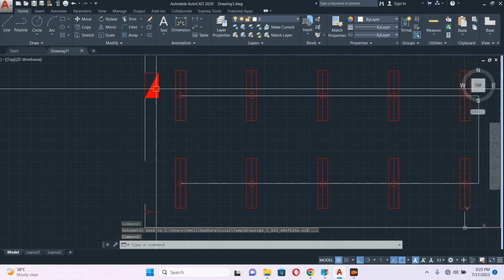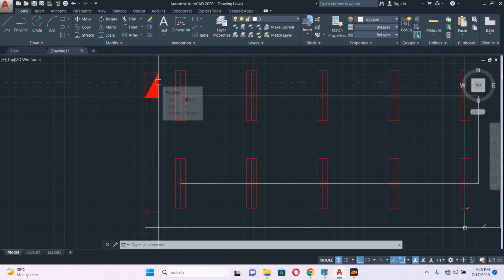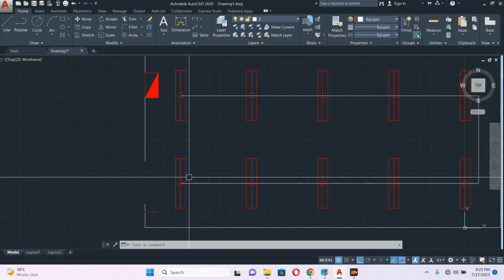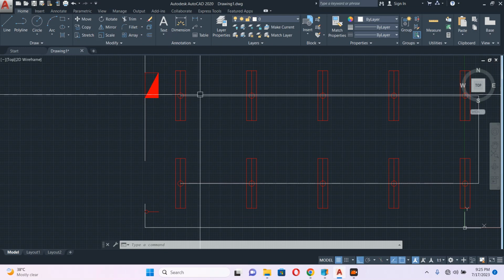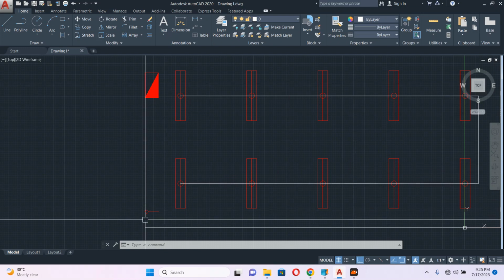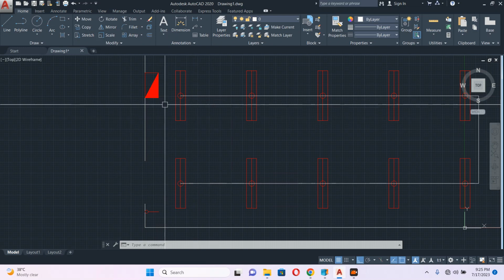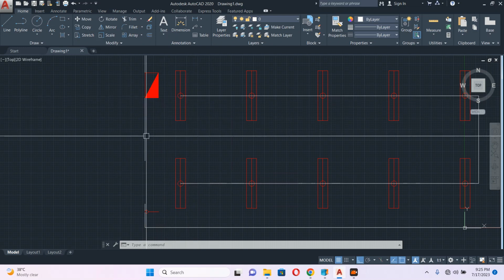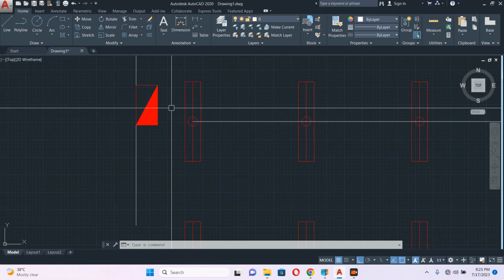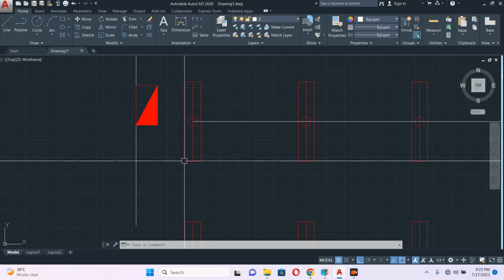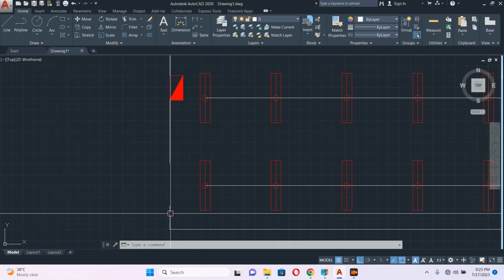So if you connect this light to here, and the switch to here, then the phase has to come like this to here, then go again. That's why the first light connecting to the DB should be connected to the switch.